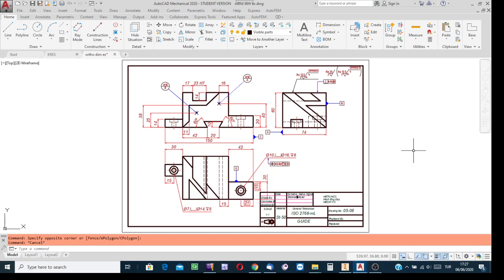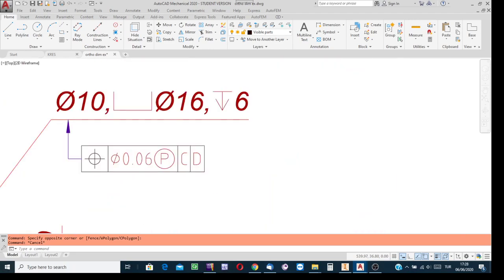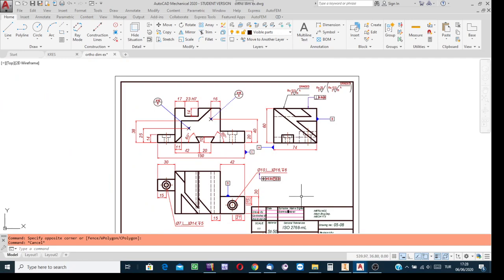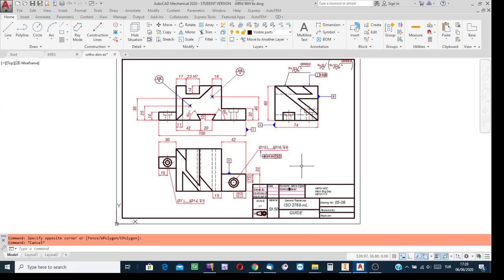And saying engineering drawing, in the classification, we mean either assembly drawing or detail drawing. If the views are for explaining the shape of a single component, then in general the sheet on which we have the necessary views of a single component and the dimensions, and of course the other things in the content of the title block. And you see here we have some annotations. Together with all of those things, if on the page we have all of such things, then we say that it is a detail drawing.